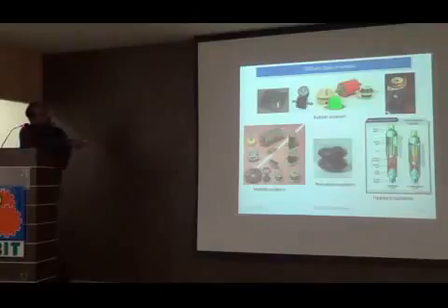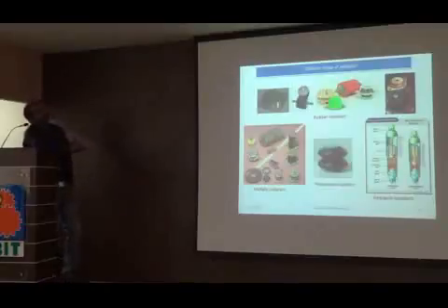These are the different kinds of isolators one can use. There can be rubber isolators, metallic isolators, pneumatic isolators, and hydraulics. These are all used for small subsystem level, package level, PCB level. These are used at a bigger level, container level, big mass, higher payloads and other things. These are again used at very low, 1 or 2 hertz kind of systems. These are used in the automobile industry mainly. We don't use these things.